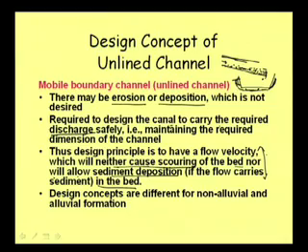In our design of lined canal, the design criteria was that it should be the best section, the most economic section. But in an unlined canal, the design criteria is that the velocity should be such that there should not be any scouring, neither any deposition. Of course, in real situations, the bed may have some erosion, because the process of flow is like that.